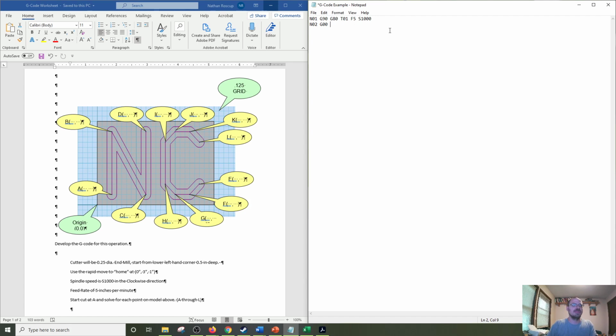So our G00 command will be X0. You can do a 0 or a 0.0. As long as you get a 0 in there, it's good. Y0. Like I said, I could leave these just 0. I think I will for clarity. And then Z0. Or, sorry, follow my own instructions here.